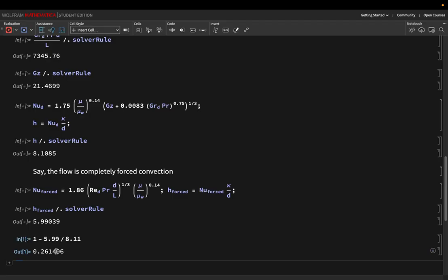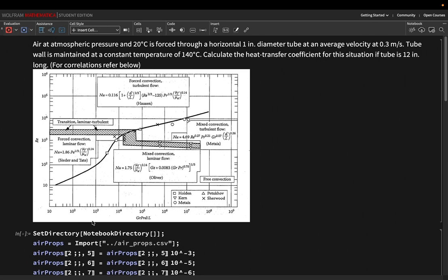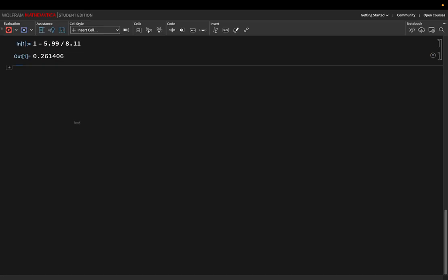Like what is the characteristic length, what is the characteristic number, what is the particular geometry they have considered, what are the boundary conditions they have used for getting those correlations, and what are the different regimes, or basically the applicability criteria for those particular correlations. For this, the criteria would be in terms of these numbers, or in terms of Rayleigh number for pure free convection, or in terms of Reynolds number for pure forced convection. So applicability of these correlations is critical before actually applying them. You'll always get some number, but if you are not sure whether the assumptions on which those correlations are derived are valid in your particular case, then you have to be cautious about using those correlations in your particular study.